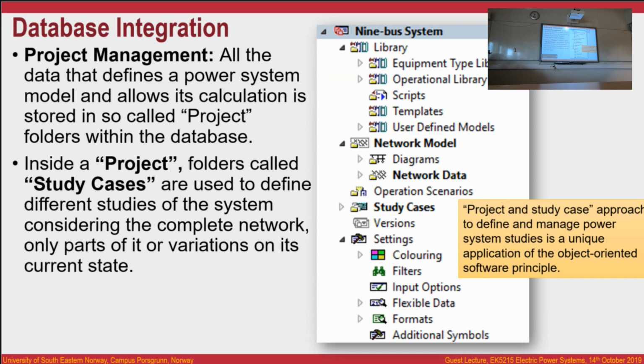Well, remember that I say that you use the data explorer like the Windows Explorer, and you can find files, and you can find your videos or your photos or your Microsoft Word documents. Are you with me? PowerFactory has the data manager. This guy here is the project. The project is the big object. Everything that you need in your power system for run calculations is inside the project.